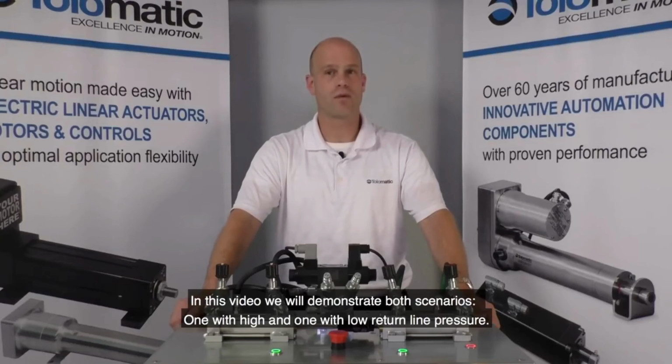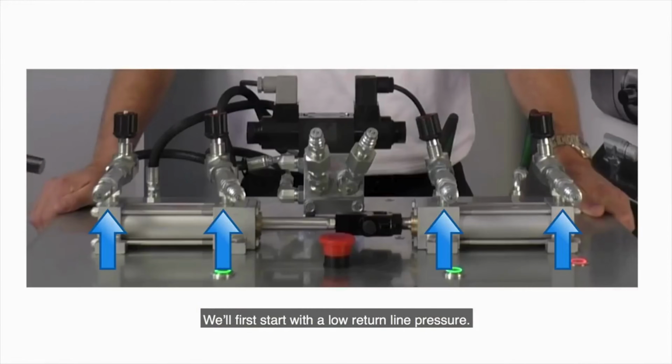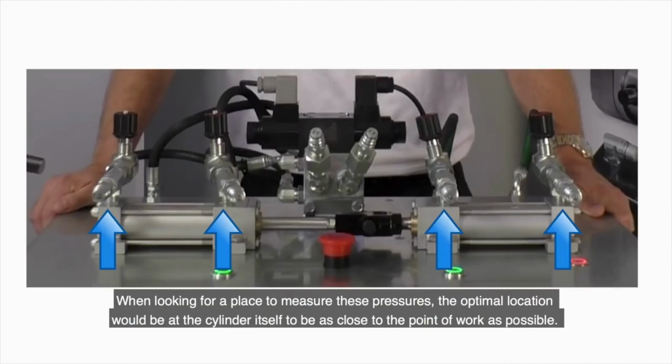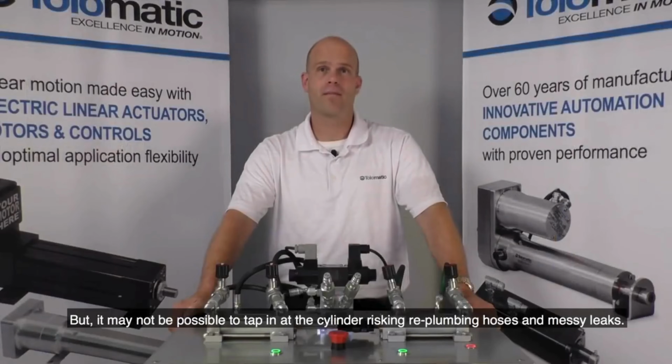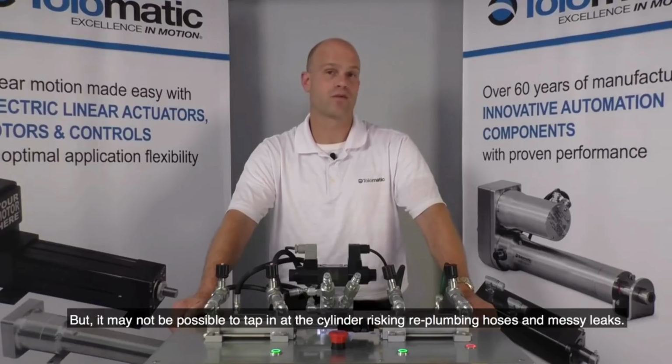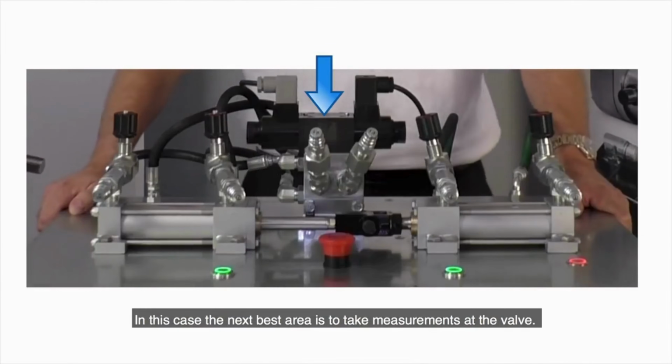In this video, we will demonstrate both scenarios, one with high and one with low return line pressure. We'll first start with a low return line pressure. When looking for a place to measure these pressures, the optimal location would be at the cylinder itself to be as close to the point of work as possible. But it may not be possible to tap into the cylinder without risking replumbing of hoses and messy leaks. In this case, the next best area is to take the measurements at the valve.